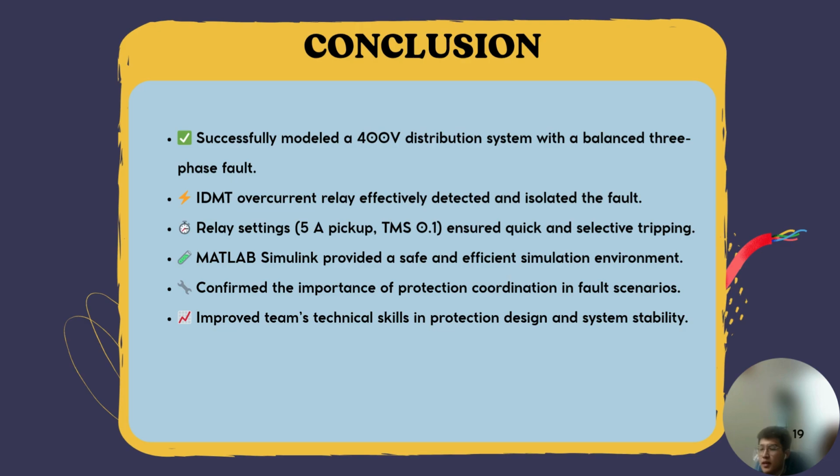And we will make it a short form. We have successfully modeled the 400 V distribution system with a balanced three-phase fault, and the IDMT overcurrent relay accurately detected and isolated the fault. The relay setting of 5A pickup and TMS 0.1 ensures quick and selective tripping. MATLAB Simulink provides a safe and efficient simulation environment and conveys the importance of protection coordination in fault scenarios. It proves the team's technical skill in protection design and system stability.